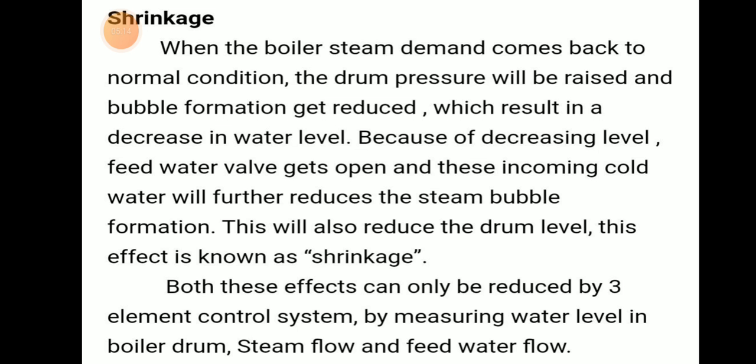Because of the decreasing level, the feed water valve opens, and this incoming cold water will further reduce the steam bubble formation. This will reduce the drum level. This is known as shrinkage.